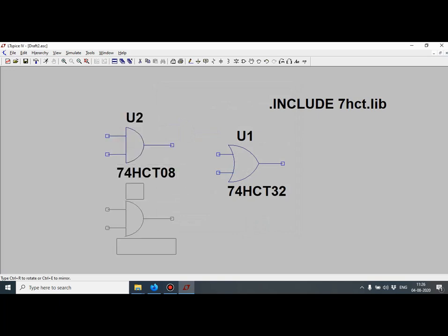That's all I require. So I have to interconnect these. How to do the interconnection? This is the wire, the blue line. I click on that wire, click here once, here once, here once, then double click here, and press the Escape button. So this has got connected here.